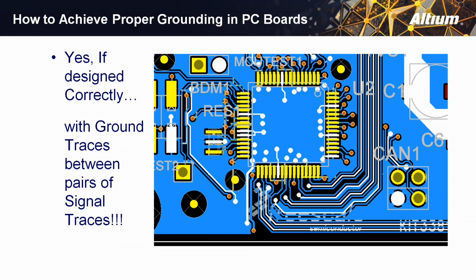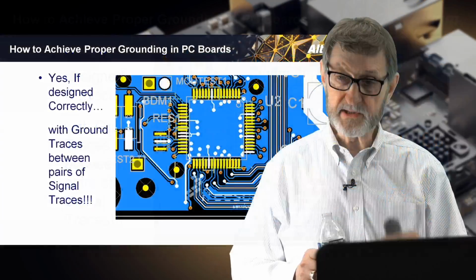The idea being to create a coplanar ground, a ground on the same layer as the signals, so the fields had a path to which they could tightly couple, to keep them from coupling through the board and into the gaps of the traces below. So it stopped the problem.